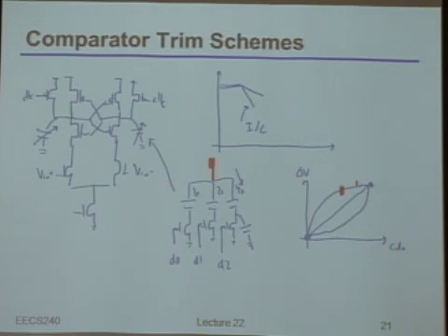Second question, or that covered it? So why isn't this capacitance control done with MOSFETs whose value is determined by that voltage difference? By which voltage difference? Where the curves spread out, it's kind of a feedback mechanism. I see. So the question was, why don't you do this with MOS capacitors whose value actually changes with this differential voltage?